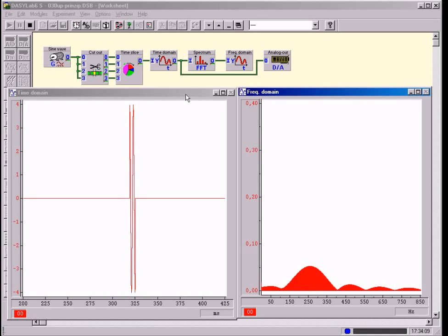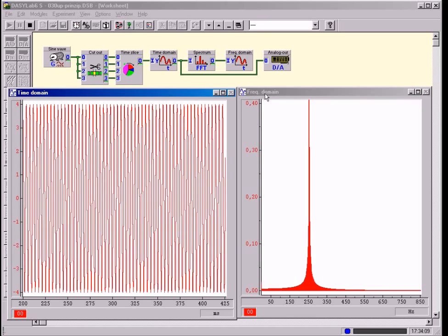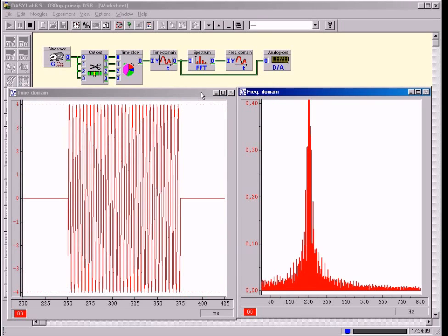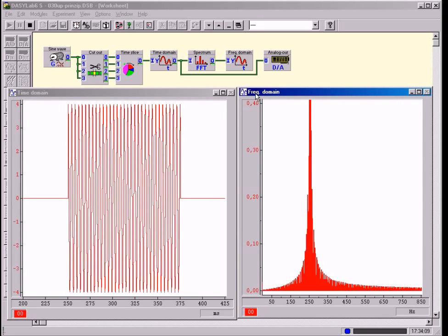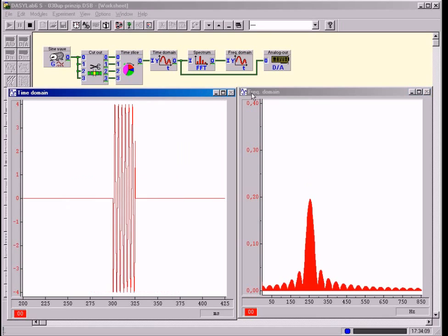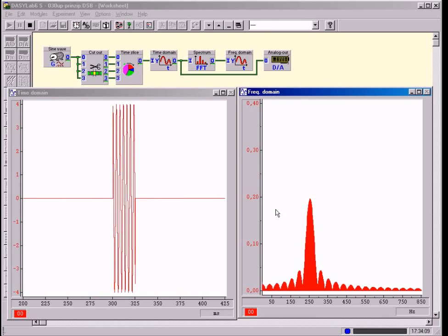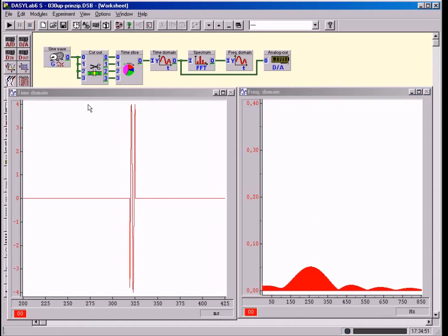If the burst finally consists of very few, for example 2 sinus periods, the original sinusoidal tone can hardly be heard through the crackling. The spectrums on the right show more specific details. The shorter the time duration delta t of the burst, the greater the bandwidth delta f of the spectrum.